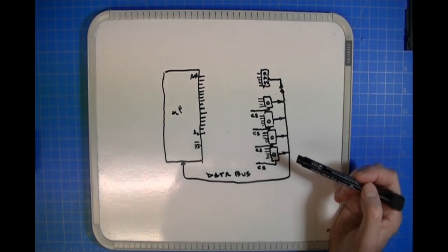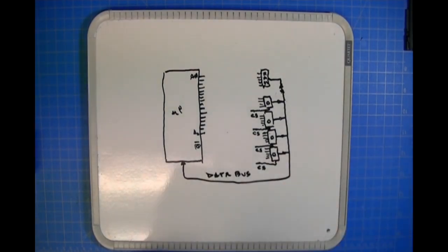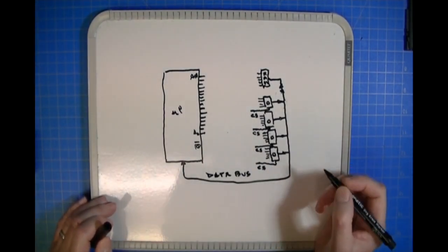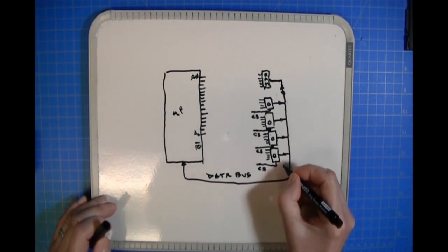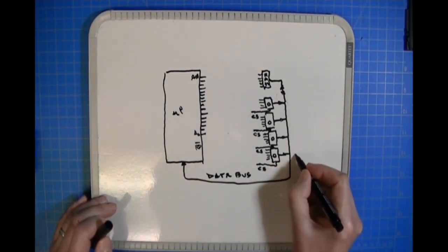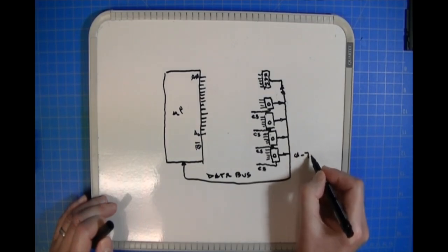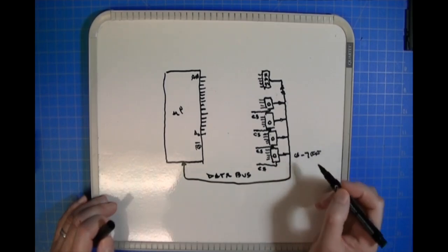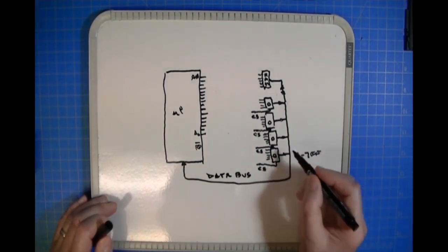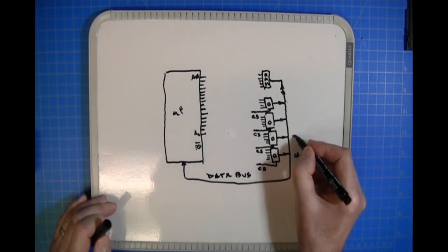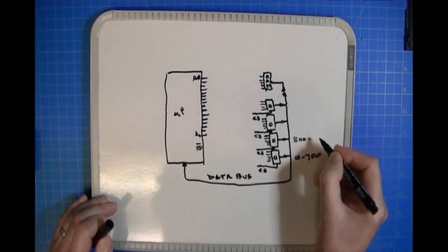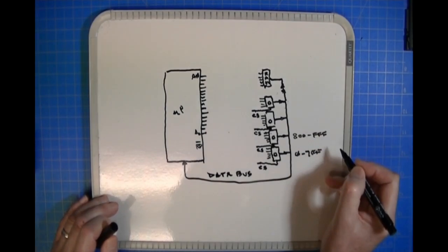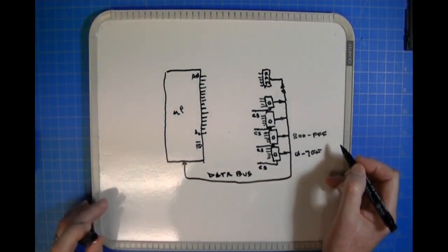When the microprocessor first starts, let's say that this is EPROM 0. Let me show you an address range here. Since it's a 2716, this one is going to go from 0 to 7FF. That's all the addresses, 2048 bytes being stored in this part. The next one is going to be from 800 to FFF, basically another 2048 bytes.